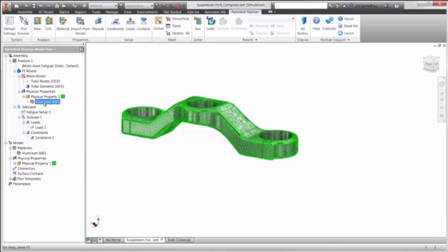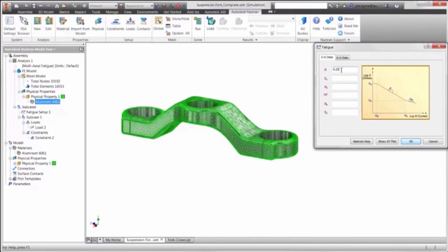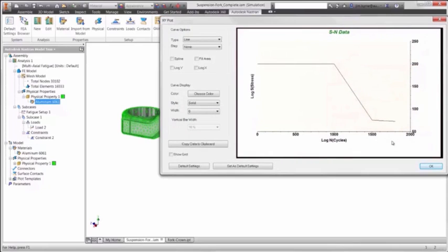There are a few changes we make to the setup, starting with the material information. Enter known material fatigue information such as slope, limit stress, and the corresponding number of cycles and the endurance limit after that value, which is often close to 0. We'll take a look at the chart to assure that the results we entered visually look correct.